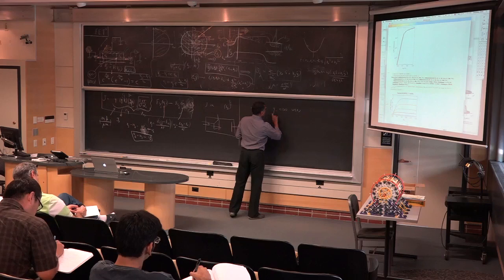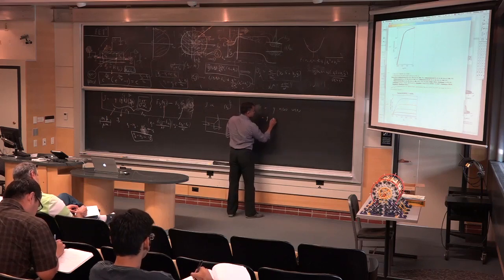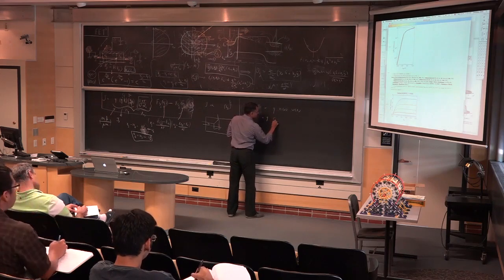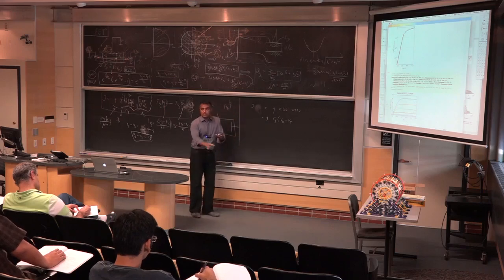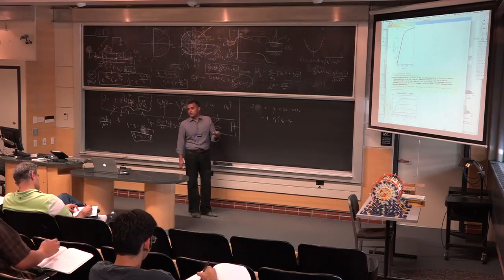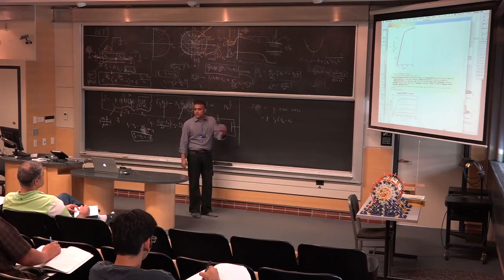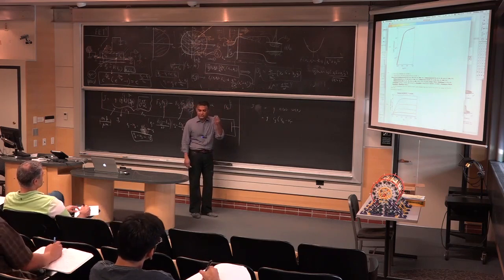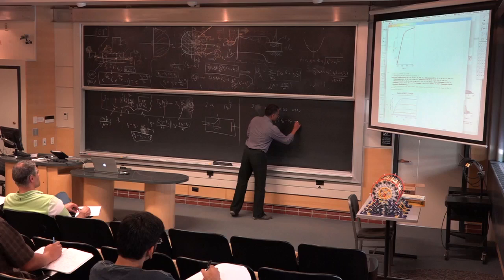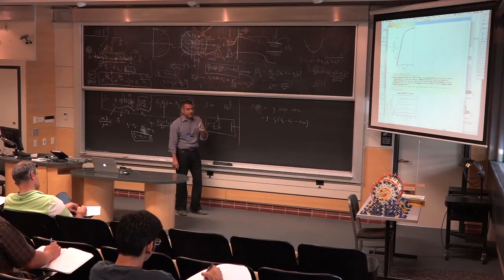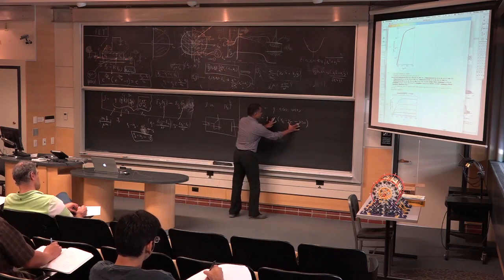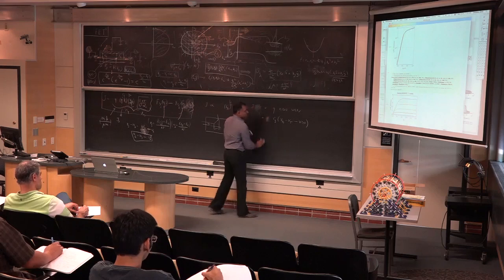And he says that the electron density is gate capacitance times VGS minus VT, because if you don't apply a certain threshold voltage, you can't put carriers in a semiconductor. That people knew even then. In a metal, you get carriers at 0 volt, but in a semiconductor, there's a threshold voltage. VGS minus VT minus that channel potential at that point x, the local potential. Now this C times V gives you coulombs per centimeter square, so you divide by Q, and this Q just goes away.